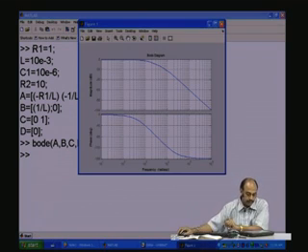So, this is the Bode plot. Now, one thing that you should notice here is that, of course, though it looks very similar to the RC circuit, the slopes are different. Here for 1 decade from here to here, it has gone down by 40 dB, whereas in the earlier circuit for 1 decade from here to here, it would have gone down only by 20 dB. So, the slope was minus 20 dB per decade, whereas here it is decreasing at a much faster rate. So, it is a much sharper filter.